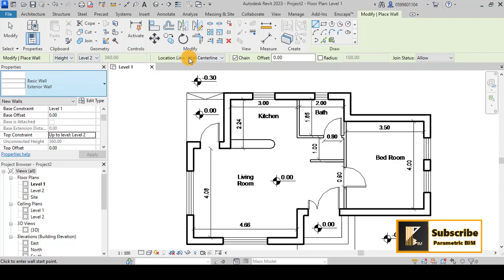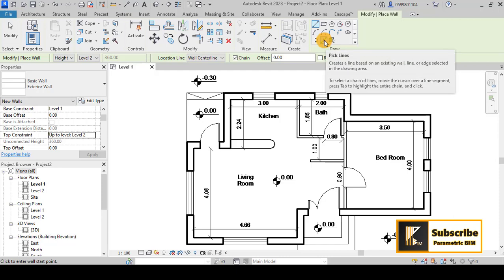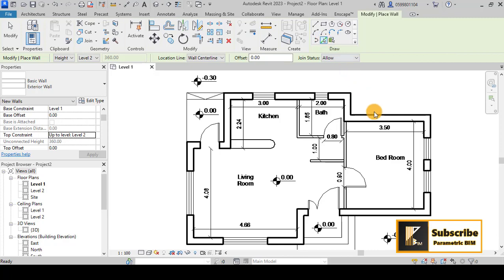For example, the location line, which is the wall center line or core center line or exterior or interior. You have the opportunity to choose from these. We will talk about that in a separate video about walls, but for now I will try to draw from the wall center line, and I have the opportunity to pick the lines. So I have these lines from AutoCAD, so I will pick these lines to draw over them.